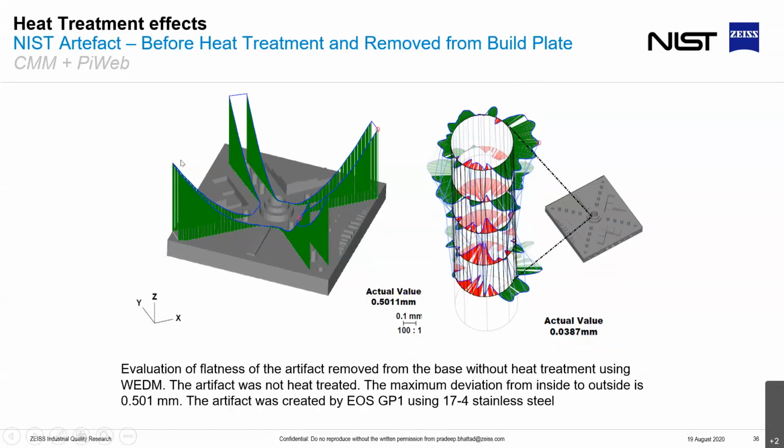Now you have much higher deviation on the edges of the build plate. And what we are also seeing on the hole is the signs were basically where it was contracting before and now expanding. But if you look at the specifications, now the part is 10 times out of spec, while the hole actually gets even better, going from 53 microns to 38 microns.